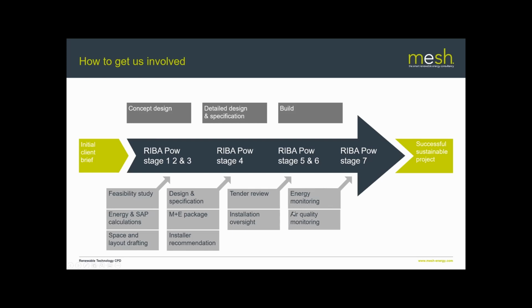It's a good idea to energy monitor these systems. It might be that you could just slightly tweak the bivalent points and give a better efficiency, because what's installed and what's designed may differ slightly. Internal gains might be different, for example, from what you thought.